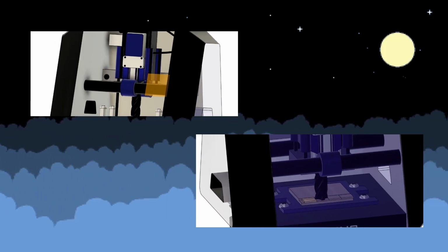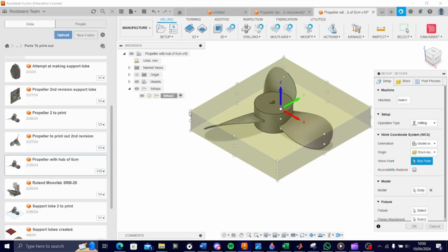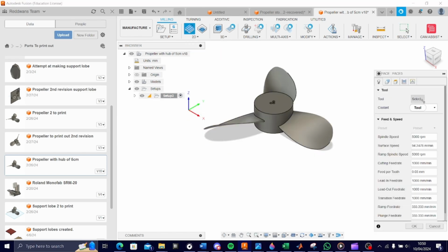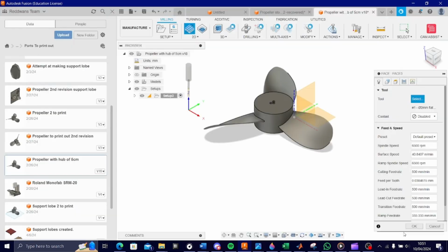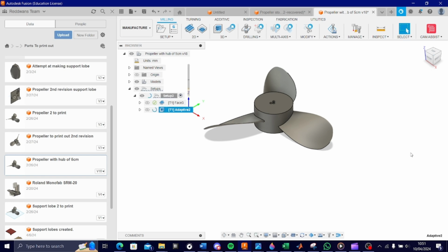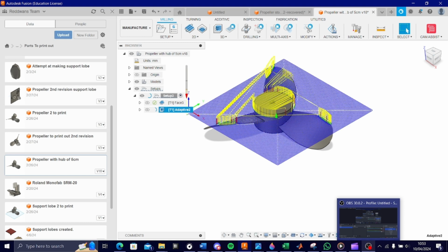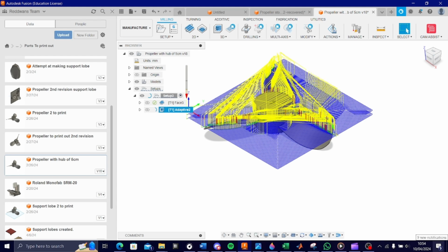The method behind producing the propeller through the CNC machine was first, within Fusion 360's dedicated manufacturing space, tool paths are generated. What this consisted of was first taking the measurements of the end mill bits and the CNC machine within the makespace to simulate them within Fusion 360. The end mill bits, which essentially act like small blades to cut the chosen materials, were a 2mm flat end mill and a 2mm ball end mill.